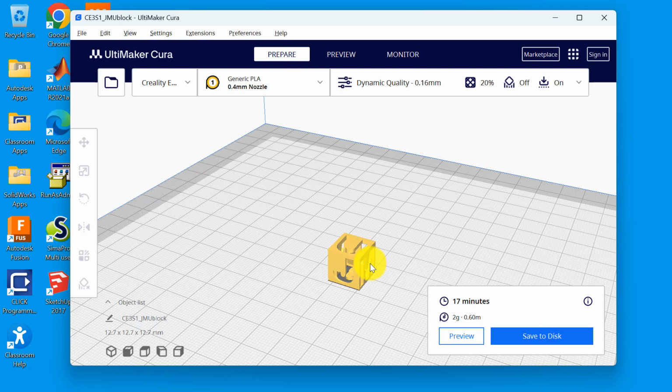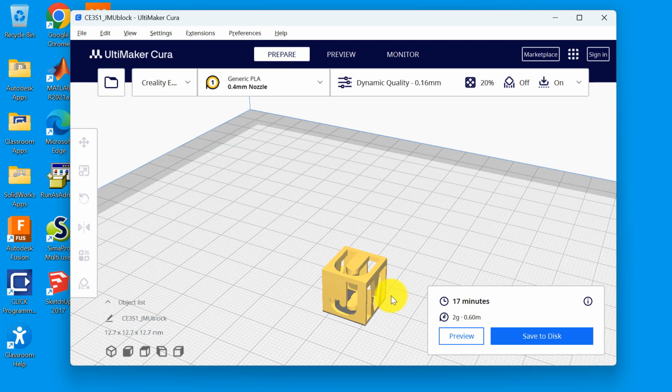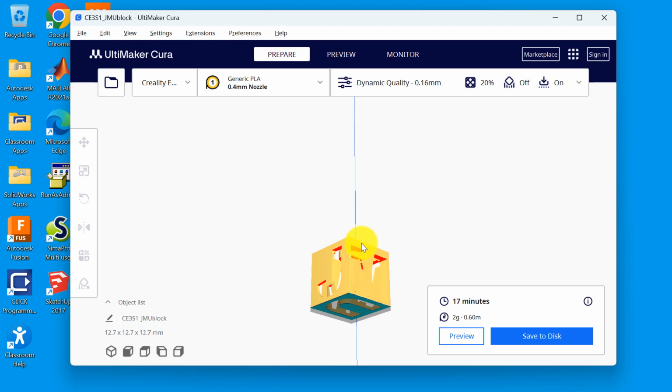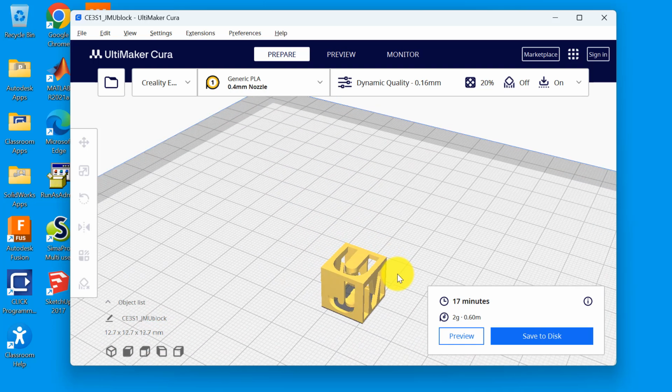This is why this software is called a slicer. It's taking the model, slicing it into layers, and figuring out where to extrude the plastic on each layer and building up those layers. If we look at this, we can see that there are parts of this model where plastic is extruded over air. There's nothing to support it, and it's highlighting those areas red. If I try to print this model, I will probably end up with what looks like a tiny ball of spaghetti.